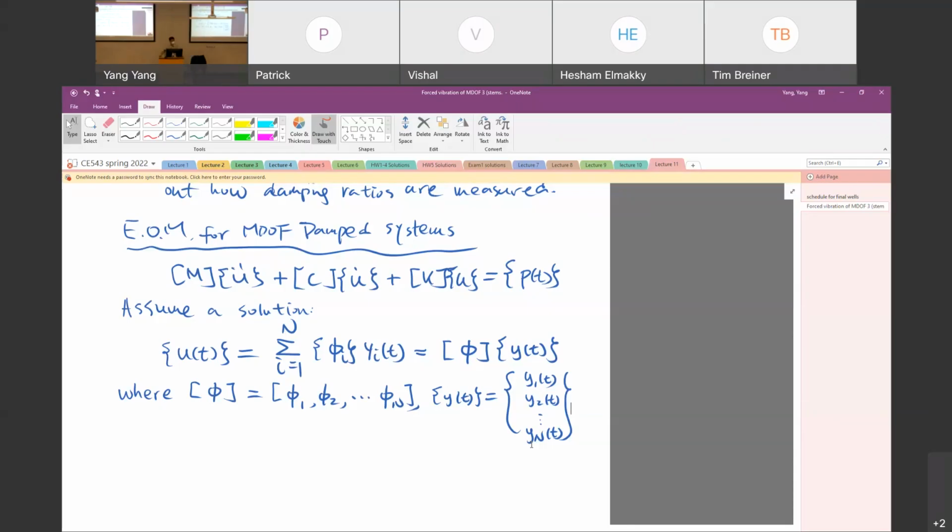Yes, we should be able to calculate the modal shapes as we did last time. Given the stiffness matrix and the mass matrix, we first calculate the natural frequencies, and the mode shapes are the eigenvectors for the mass matrix and the stiffness matrix, which we did last time.